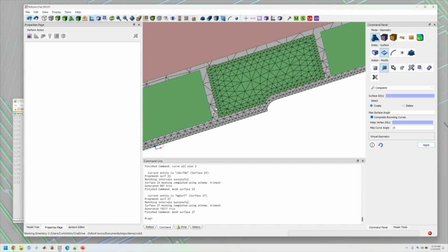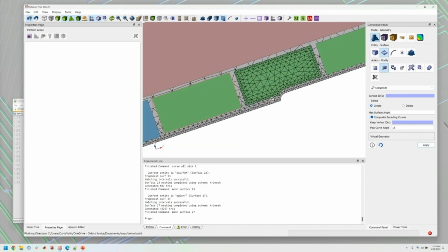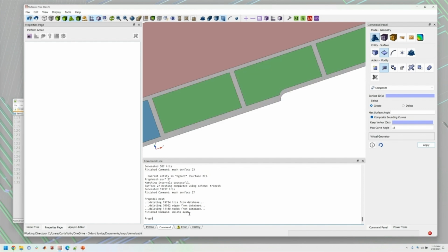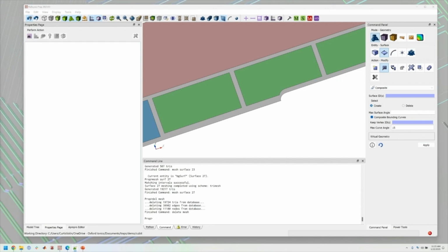So we want to actually cut up this lower ground plane into pieces that match the upper ground plane, so that it will mesh triangles that aren't necessarily identical, but are similar in scale as you sweep across this trap. So delete the mesh that we have, and then we want to do an imprint command.